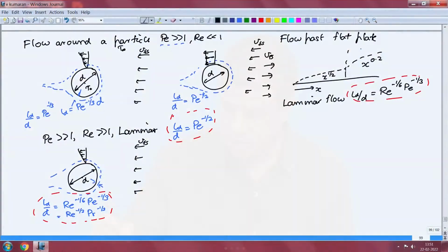In the last lecture, we had briefly summarized the characteristic length for diffusion for the case where the Peclet number is large, so that convection is dominant compared to diffusion. In that case, the mass or energy that is diffusing out from the surface is rapidly swept downstream, and therefore, the variation in the temperature or the concentration due to the surface boundary condition is restricted to a thin region close to the surface, whose thickness is much smaller than the characteristic dimension of the object.